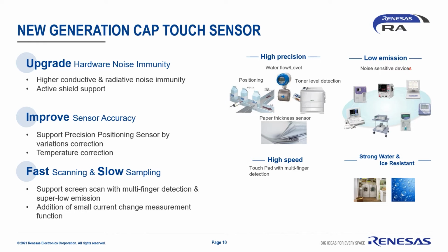It is offering more, so we upgraded the hardware noise immunity with shield support and also added multiple frequency scan. We improve the sensor accuracy by adding some register access to improve the signal to noise ratio or the resolution. We also have a hardware structure in order to manage temperature drift.